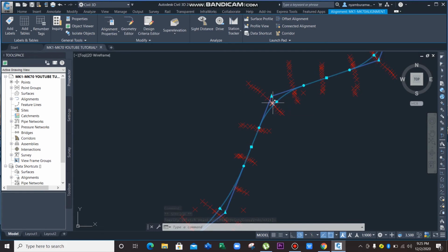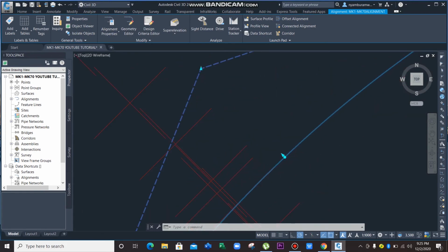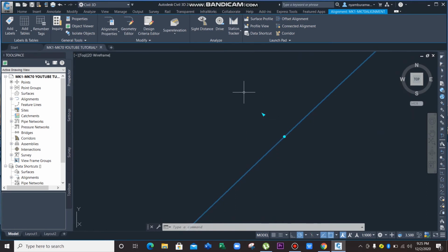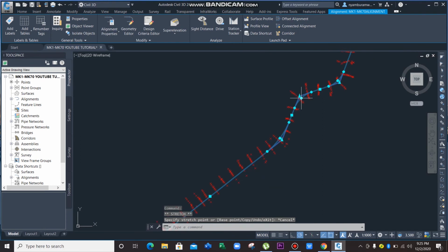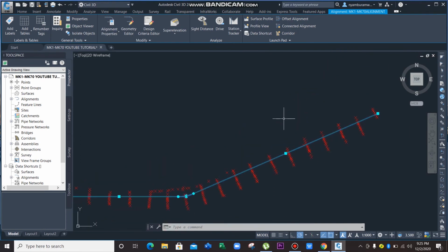And then finally, the last grip is your radius grip, which is this small triangle right here next to the grip that forces your curve to pass through wherever you want. This right here is your radius grip, and you can use it to change the radius of your curve. So that's it.